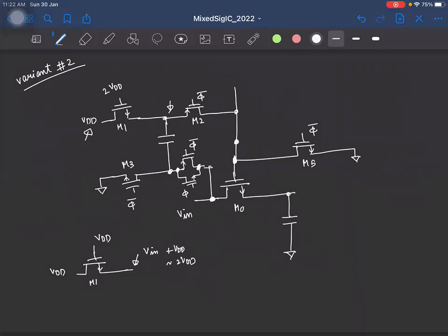And the switch turns off. Okay. So if we want to use an NMOS switch, the gate voltage has to swing from VDD to 2 VDD, right? So this means that instead of having a clock going from 0 to VDD, we now need a clock that is shifted up, right? So it has to go from VDD to 2 VDD. So let me draw it like this. It has to go like this, right? So if this is 0, this is VDD, this is 2 VDD, right?